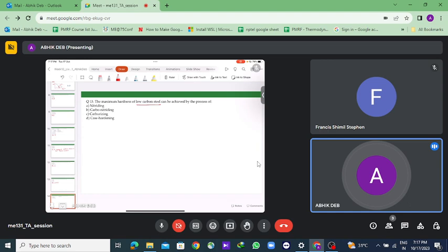So it is either carbonitriding, nitriding or carburizing. Of these, it has been observed that nitriding has the maximum hardness-giving capacity for low carbon steel. So the correct option will be nitriding. So if asked why not martempering, don't say that it is about the surface or the bulk. It is because the carbon content is low, so the formation of martensite will not give that much high hardness.